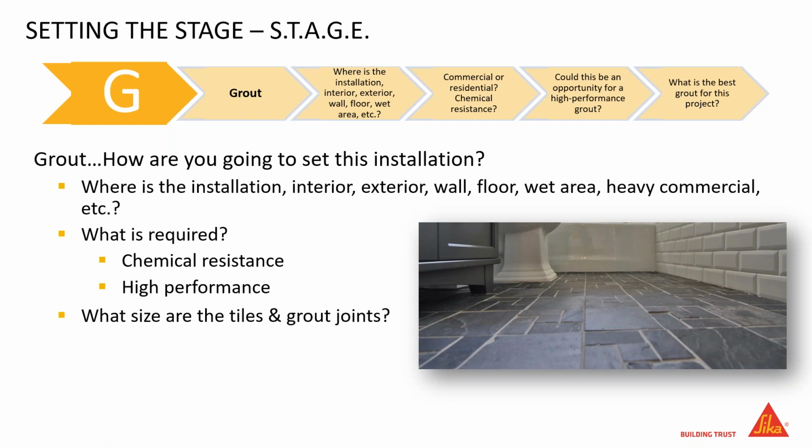I had somebody yesterday tell me, oh my gosh, did you know that XYZ manufacturer's coming out with 1/32 inch spacers? It's like, yeah, I heard that, but really that's a non-go in our industry. Tile size, tile warpage, and caliber determine the size of spacers or grout joints that we're supposed to have on those jobs. But we know what the homeowner wants, and what the homeowner wants, typically the homeowner gets. So we need to know those things.